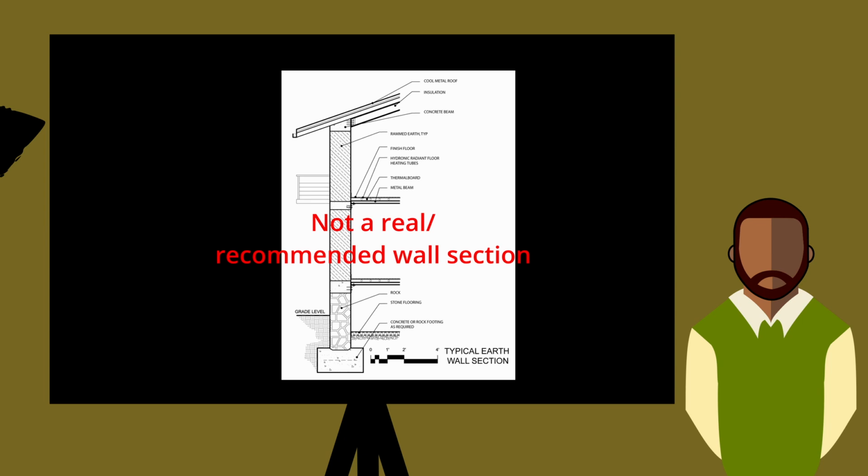I'd say if it is over 9 feet, so if you are 10 feet or more, then it's 2x6. I would never put that on paper, right? But the IRC does. If you guys want to play with fire, by all means, the IRC seems like a great place to point if the flames rise.